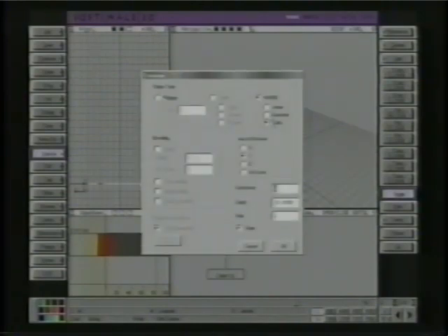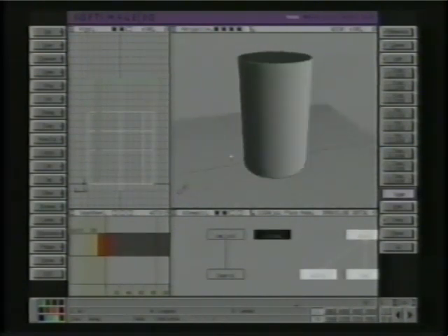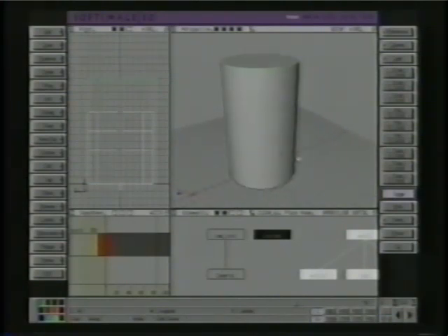extrusion. Then I'm going to choose NURBS cubic, Y, subdivision of 6, and a depth of 15, and then leave the close option on. What that does is creates a cylinder that's capped on the top and the bottom. This is actually inverted. I'll need to invert that. I just have a hotkey of I to do that. It's also located under Effect Inverse.